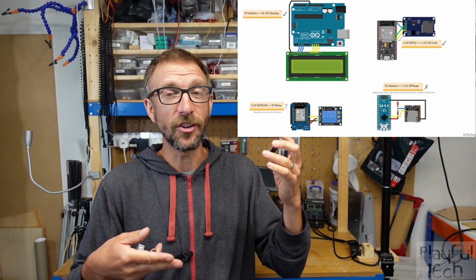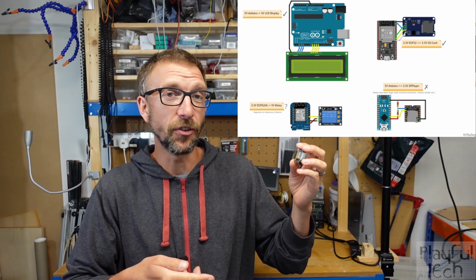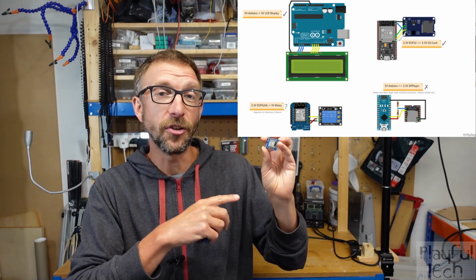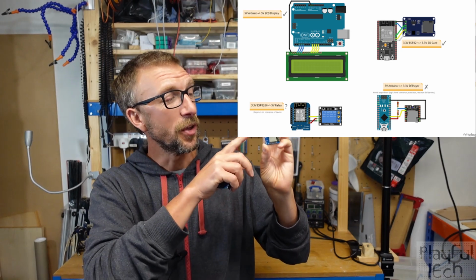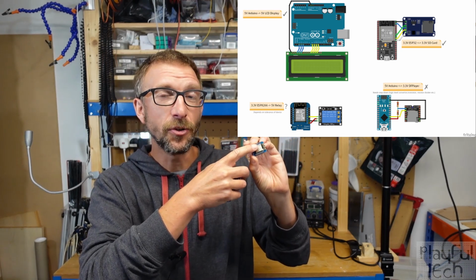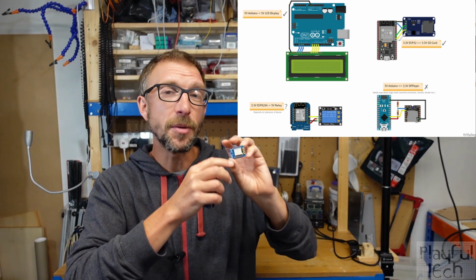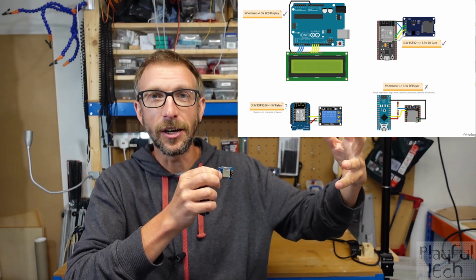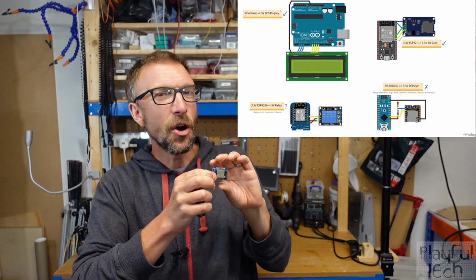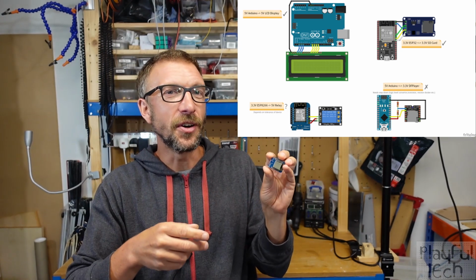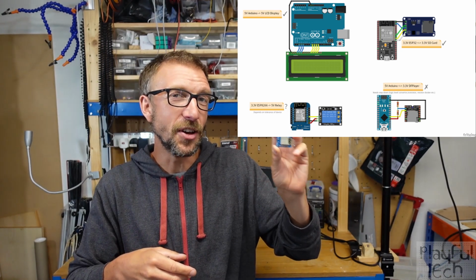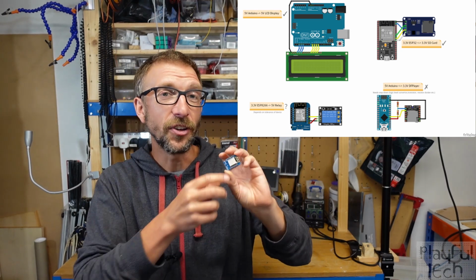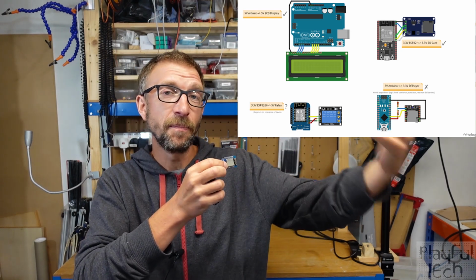Many will still interpret 3.3 volts as high, in which case you might still be able to connect them directly. When the processor here sets a high signal, it only gets as far as 3.3, but so long as that is within the tolerance of the sensor, that's still high. But that's going to be on the limit of many devices.